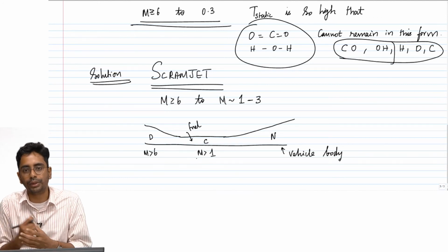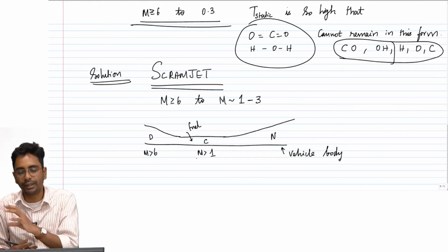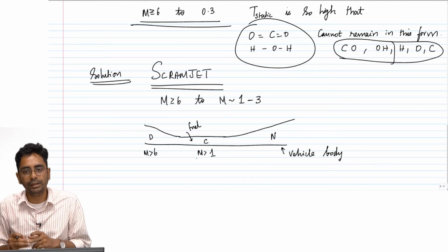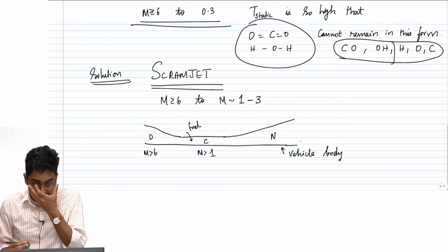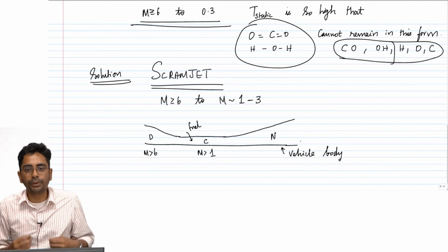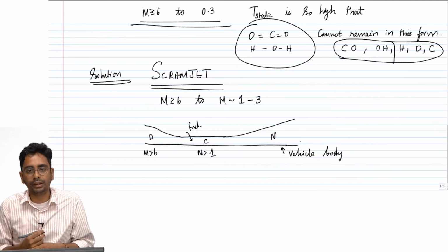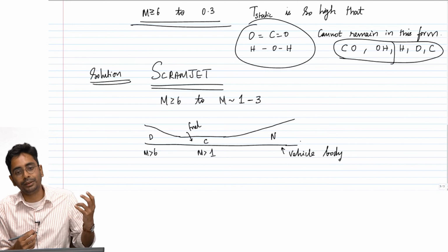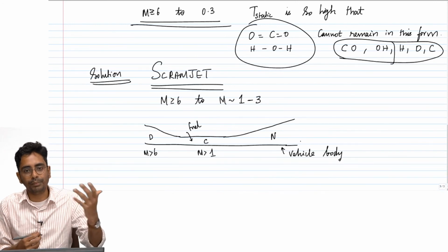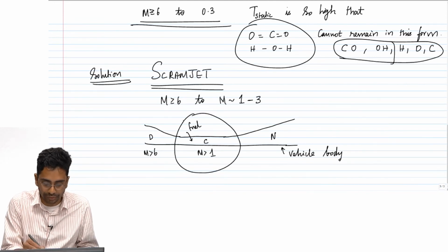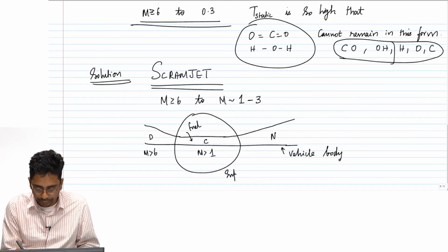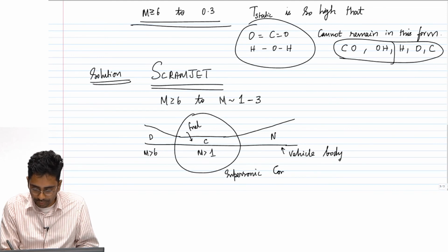The reaction will continue to remain net exothermic, adding enthalpy to the stream, and therefore when it is accelerated through a nozzle, net positive thrust can be produced. This is the reason why a ramjet for Mach greater than 6 is called a scramjet, because combustion happens under supersonic conditions. Supersonic combustion.